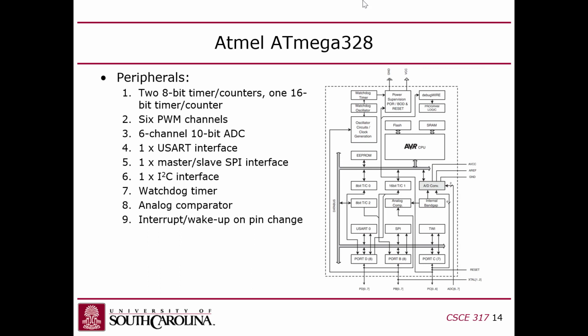Yes? I think I looked this up like a year ago, but I think I2C is a way you can talk to multiple different peripherals on one of the two wires? Yeah. So you can index through them? Yeah, that's what it's for. I was just wondering what the acronym meant. It's IIC. But we'll be using that for that purpose. We're using I2C to talk to the accelerometer sensor, and SPI we're using to communicate with the LCD screen.